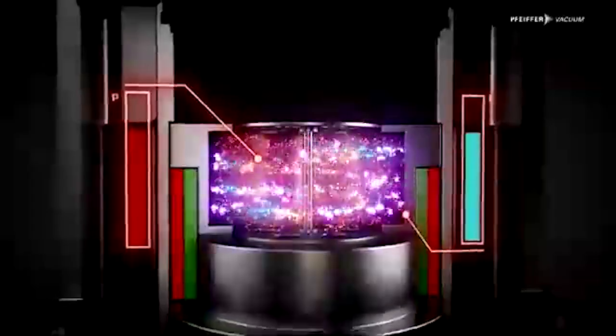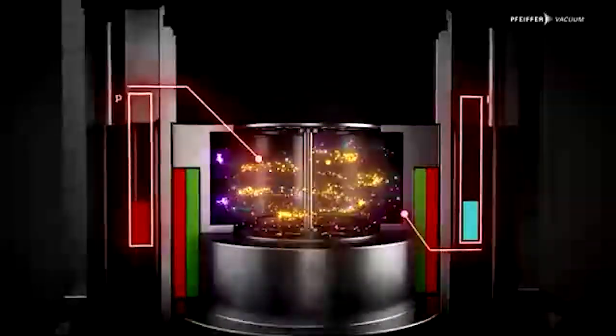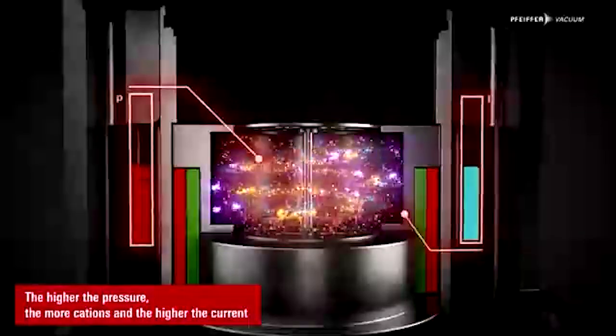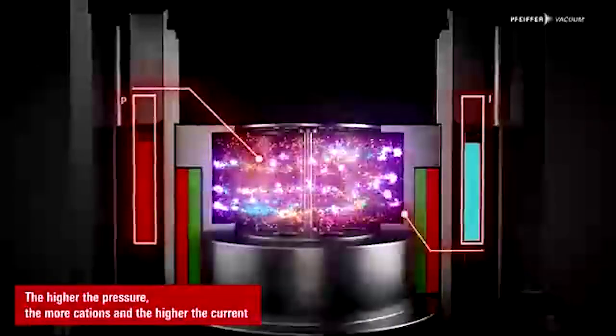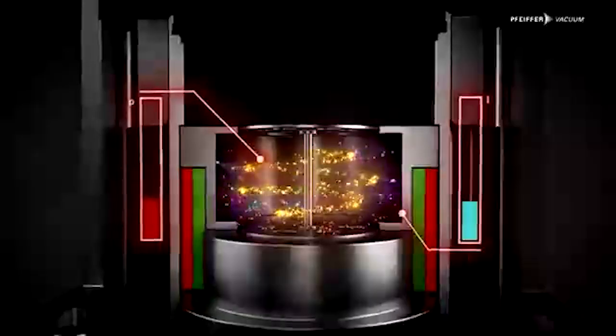Right, so pressure, current. You've got helical paths for the electrons, they ionize the gas. It's all in that little container. They have gauges now which are composite gauges, and they may combine the features of the thermocouple gauge and the cold cathode gauge in one. And those are $3,000 now, something like that.